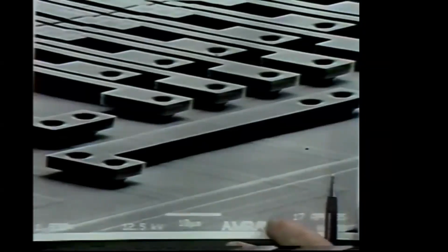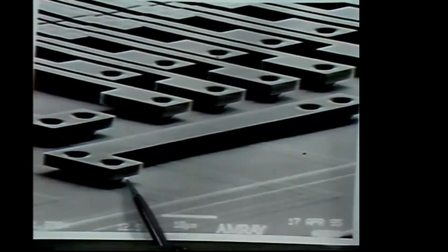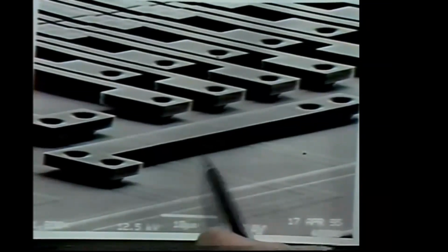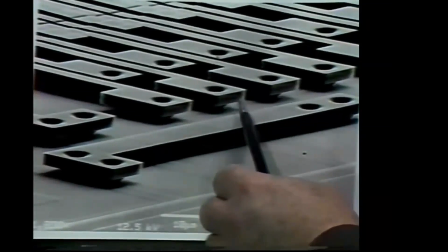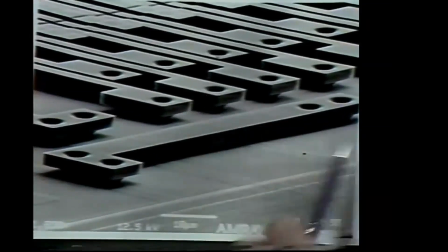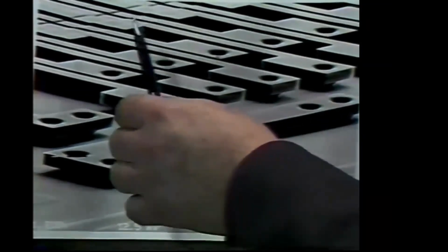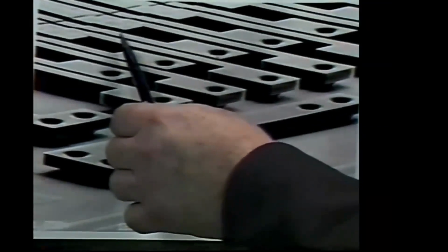A brief look at the actual material. You can see in this SEM photograph that the polysilicon material of 2 microns in thickness is indeed suspended above the substrate. Looking under one of these anchors, these are the anchors to the substrate. And there are very small stress gradients within the material, which you can see by looking at the ends of the fingers relative to the things that are fixed above the substrate.